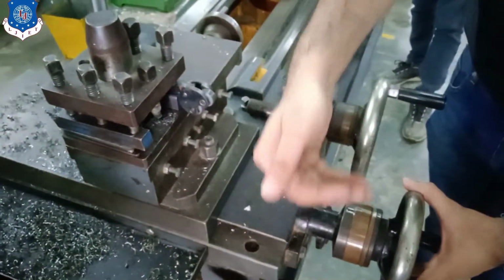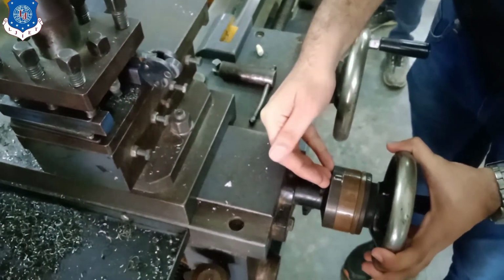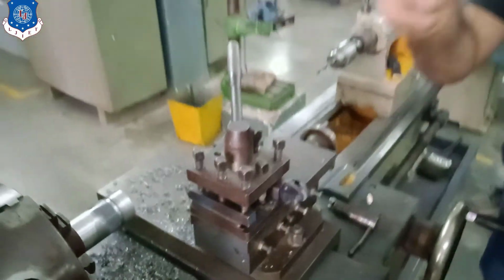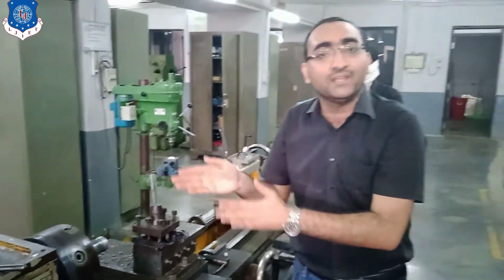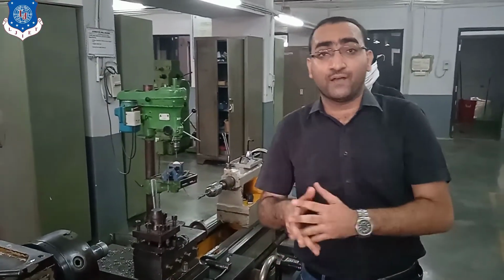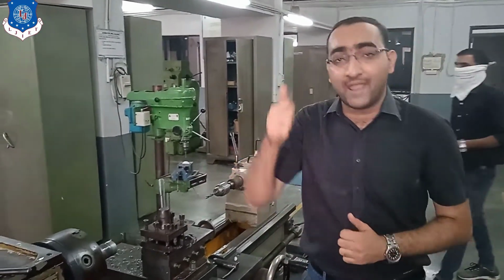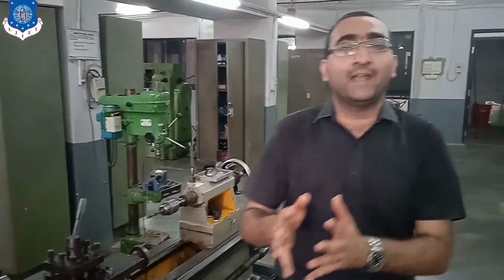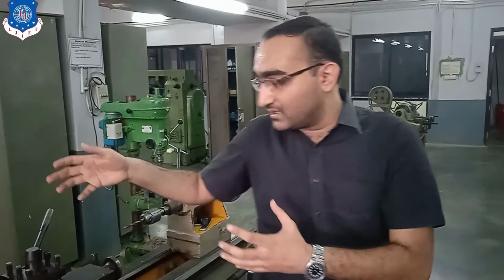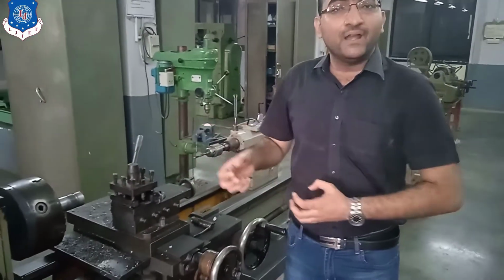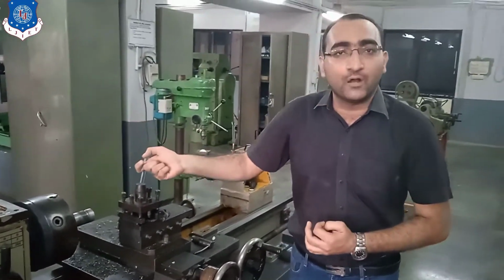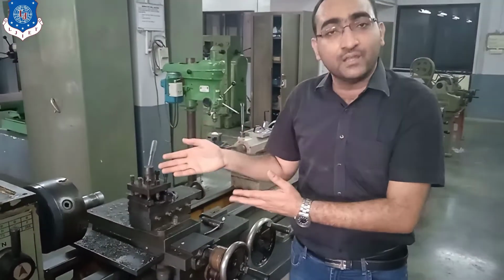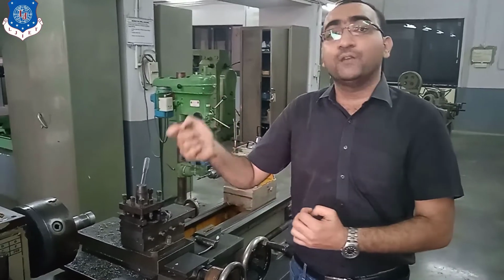After that we will move once again from 2, we will go to the 4 option. Once again we will be doing the threading. So gradually we are inserting the tool inside the workpiece. Why? Because if we go in one shot, your tool will definitely get broken. As during the working operation you might have seen the flames and smoke coming out, that was because of the overheating. So the overheating is a problem and it will always be there.